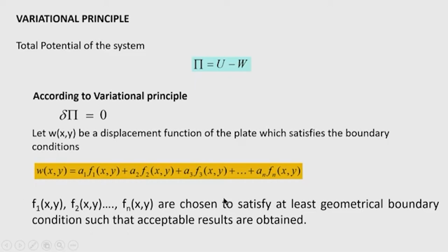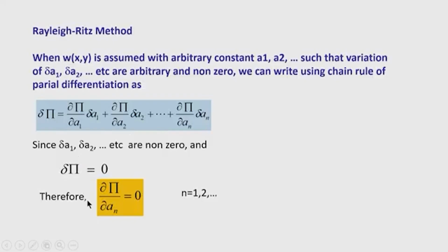So, the free vibration equation can be solved for different boundary conditions to find out the eigenfunction, and that can be chosen as a trial function in the plate, as has been suggested by Blasov. But this method of taking the eigenfunction in the plate problem requires a lengthy calculation, but it will yield an accurate result compared to some trial function that does not completely satisfy the boundary condition. Okay. So, let us discuss what the Rayleigh method is.